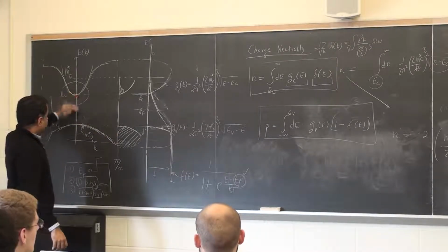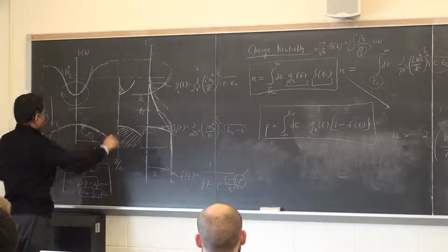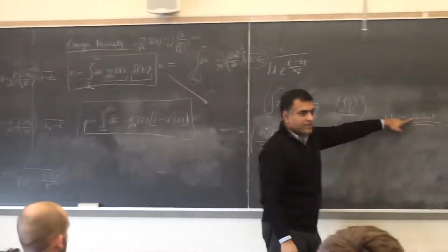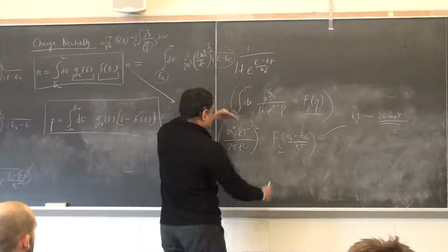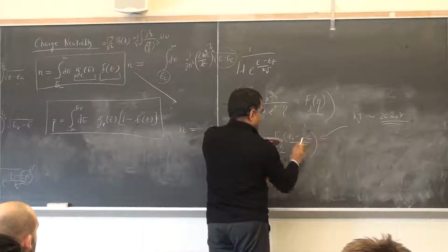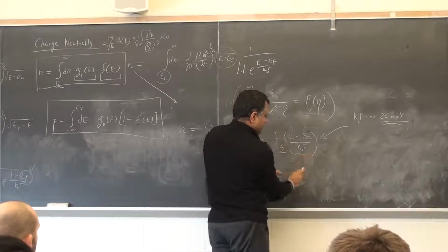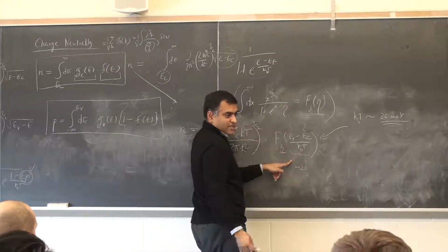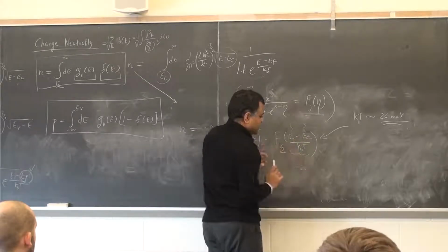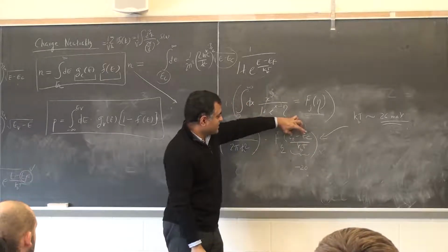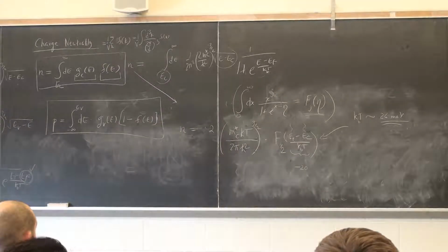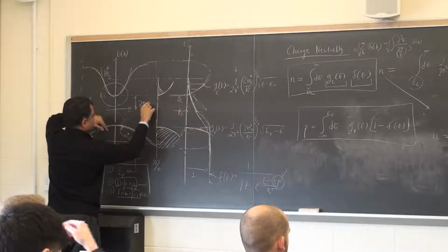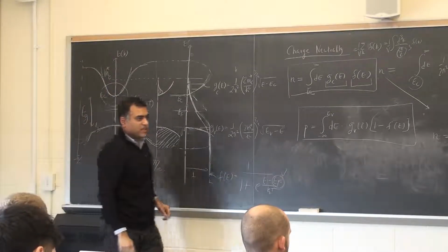So you can see if you are half the band gap, that's just in the middle, that's 500 millielectron volts. So that's 20 times that. If the Fermi level is 20 kT below, then what is the argument? Minus 20. Let's say EC minus EF is 20 times, just for argument's sake, kT. Then the argument is minus 20.